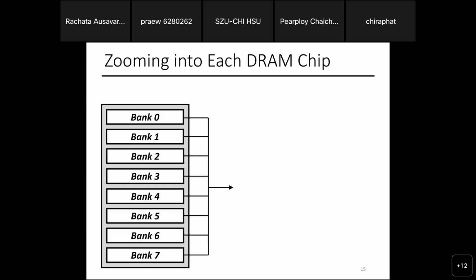The reason why you have multiple banks is that each address is similar to the cache set. What about a cache set? Every single address is mapped to a set, and only that set. Every single address will have its own cache set that you go to. Same thing here. Every single address has its own DRAM bank ID that you go to.